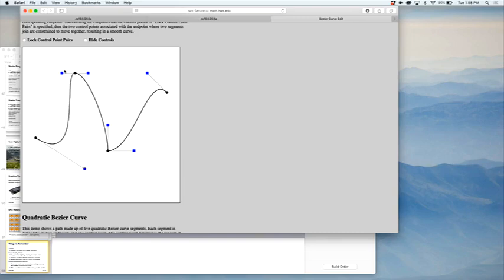Here's a control point here that is defining the tangent of this curve as it approaches B3 for this first cubic Bezier curve here. So I can move this around. Notice if I do this, the entry tangent is potentially different than the exit, than this next cubic Bezier segment here. I can move this to make a corner if I want, like that. So I can get a little corner here.